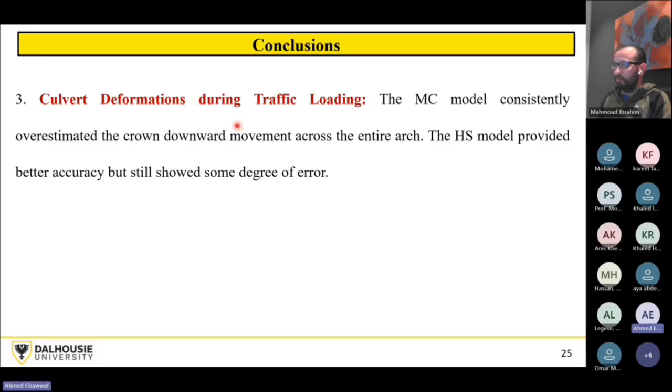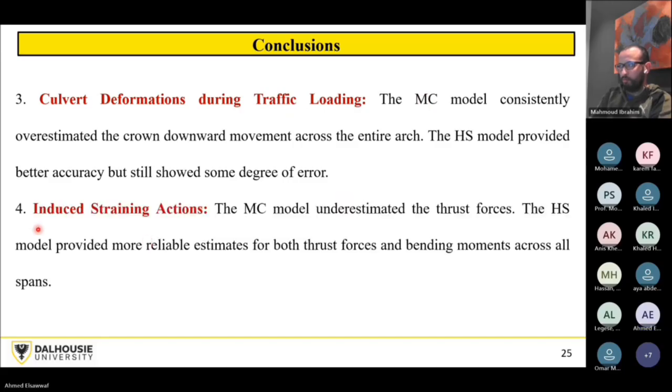So as you see from these three points, there is a big problem in considering the culvert deformations, due to the rebound of the structure after removing the compaction in the Mohr-Coulomb model, and due to the stiffness applied to the soil in the Mohr-Coulomb model, which is one third of the unloading-reloading stiffness that we have in the HSS model.